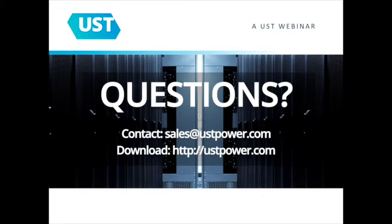Wasn't there an efficiency where typically they oversize the UPS often for redundancy? Well, you're never going to purchase a UPS to match the load. You're going to oversize it for expansion or whatever it may be. So when we look at an application, we're going to try and match the load. We don't have any reason to oversize unless there's a need to.